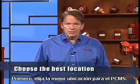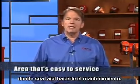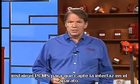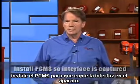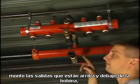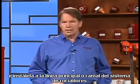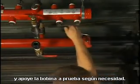First, choose the best location for the PCMS. This location will ideally be in an area that's easy to service. If there is an air and water interface in the system, install the PCMS so the interface will be captured in the device. To install the test spool assembly, position the outlets so that they are on the top and bottom of the spool piece. Then install the test spool into the sprinkler main or branch line using the grooved couplings and gaskets provided, and support the test spool as needed.